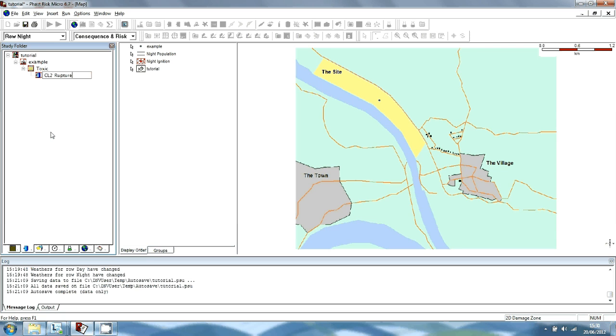Use the vessel pipe source model when you want to perform a dispersion and effects calculation for a release from a containment, and you want to use the program's inbuilt discharge calculations to determine the state of the material after expansion to atmospheric pressure, which is the state required for the start of the dispersion calculations. The program contains a second source model, which is called a user-defined source model. This model does not perform discharge calculations, but instead allows you to specify directly the state of the material after expansion to atmospheric pressure.